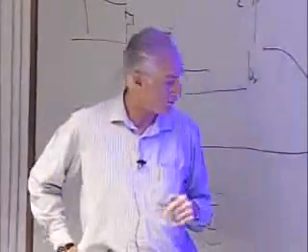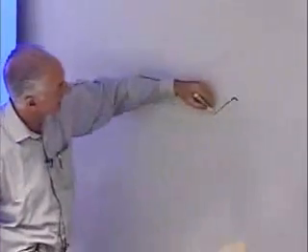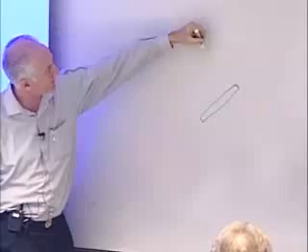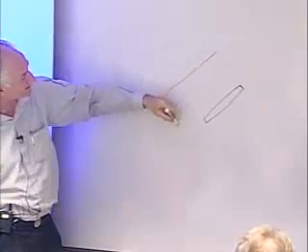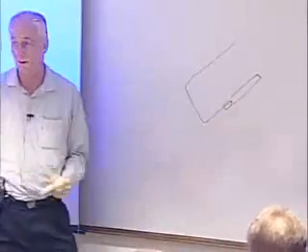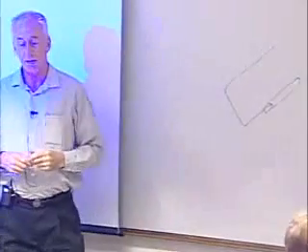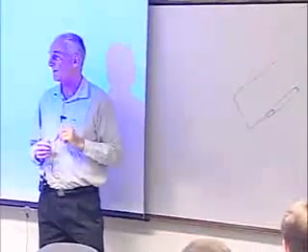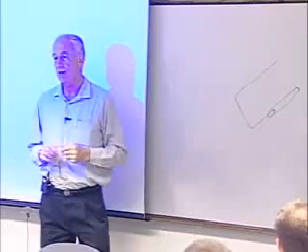They go into, if this is your landing runway, a regular airplane will typically do a downwind, a base, and then come in for a landing. With the shuttle, we actually want a much larger pattern to give you more opportunity for energy control.